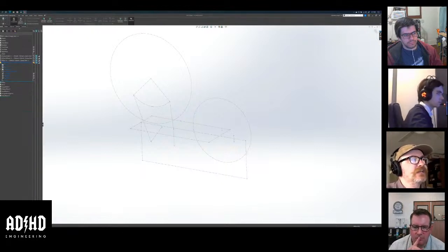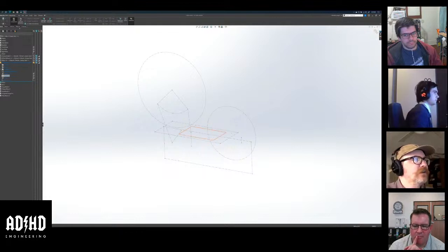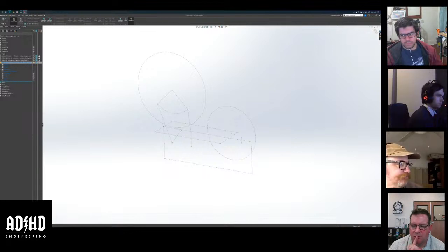So normally I would expect that to automatically have happened. So there's probably a setting I need to change in SolidWorks to make that happen automatically. But either way, because of that, my origin planes are the same as the assembly origin plane. Yep. And I am fixed, but if I float it, then those planes will lose their relationship, and I'll have to mate them after that.